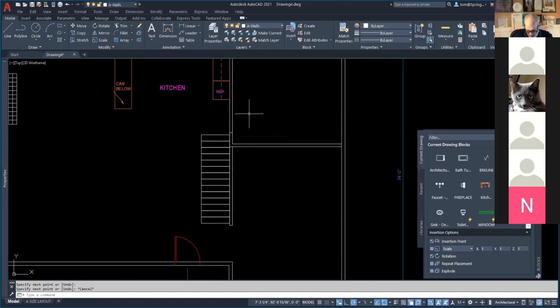And then that's going to be a 3 foot door. It's going to go down here and go over 3 feet. And then back over to here, I'm going to trim it up. So I'll go to trim, and I'll get rid of these here, this and this, like that. Okay, so you got that. Now at that point, I've got these right in place. Okay, so I've got all those.